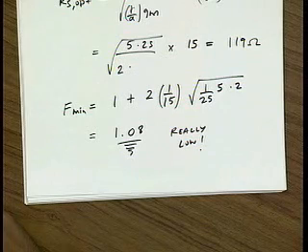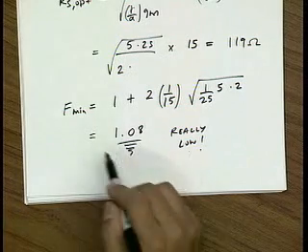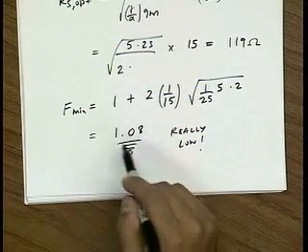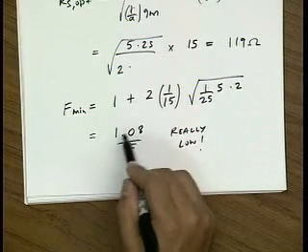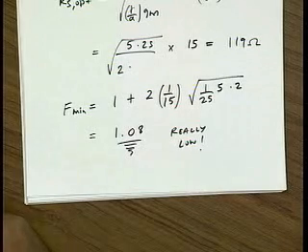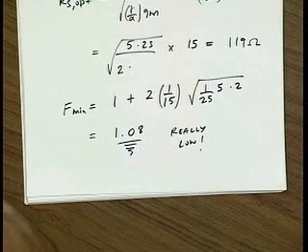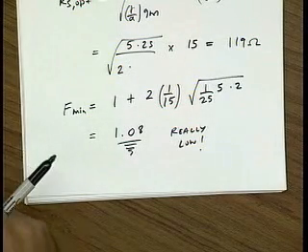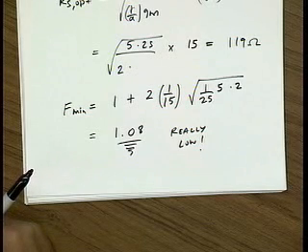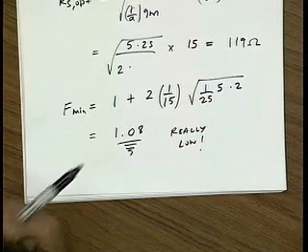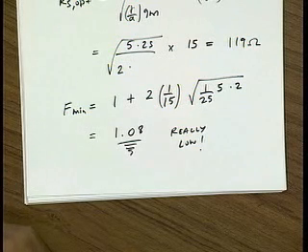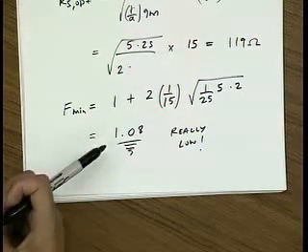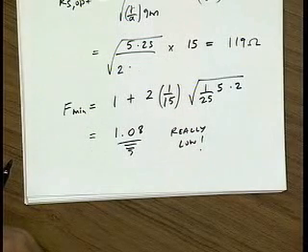Okay, so the point is that this is really phenomenal. If you could achieve a noise figure like this, it's basically just a 10% perturbation on our SNR as we go through this device. This is really great. If you could actually achieve this, you'd be very happy. Remember last lecture we looked at the common gate device and we found the noise to be at least a factor of 3 to 4. Compare that here. Really, this is good.